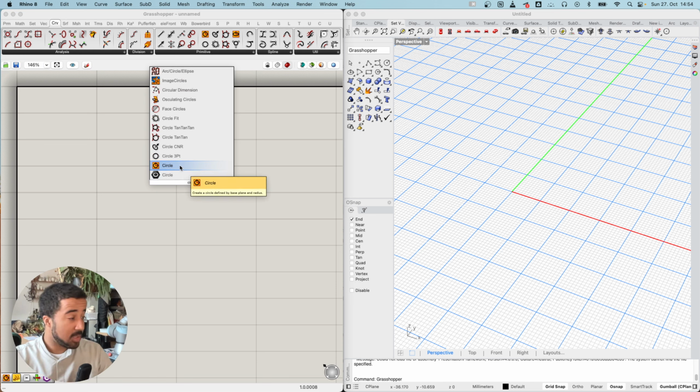Full Names option. If you don't draw the full names, the components might be more compact and your definitions might look less cluttered. However, it's often quite confusing because it's not always obvious that cir means circle, and sometimes the inputs and outputs have the same letter for different kinds of outputs. So P is not always for plane, it might also stand for point or parameter, and so if we draw the full name, then we know exactly what our inputs and outputs mean.